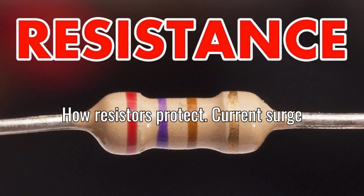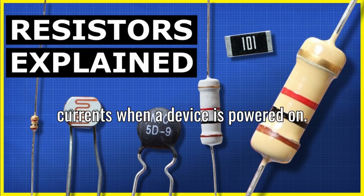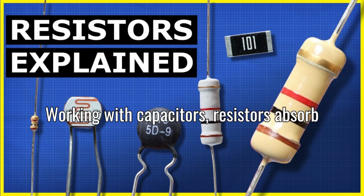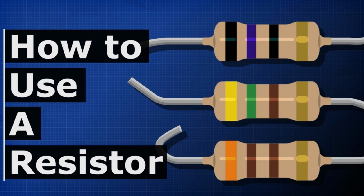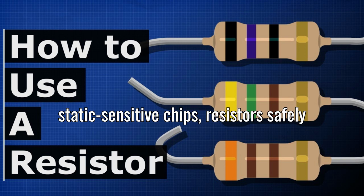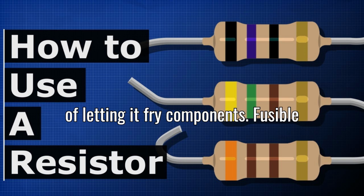How resistors protect. Current surge control. They limit sudden inrush currents when a device is powered on, like preventing a light bulb from popping when first switched on. Voltage damping. Working with capacitors, resistors absorb sharp voltage spikes, called transients, that can come from power lines or switching devices. Static discharge safety. In circuits handling static-sensitive chips, resistors safely bleed off unwanted charge buildup instead of letting it fry components.